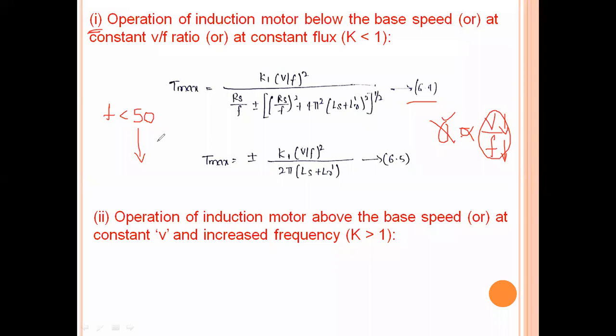Therefore, an increase in the flux will saturate the core, which will increase the magnetizing current, which also distorts the line current and voltages presented in the induction motor. Not only that, it will also increase the core losses and stator copper losses, and also produce acoustic noise.